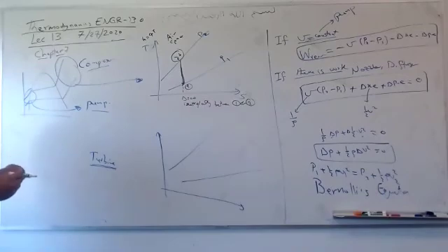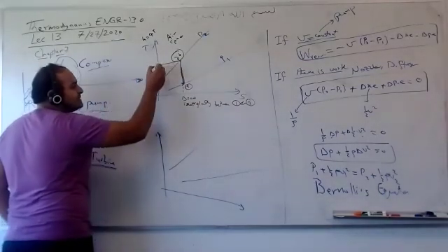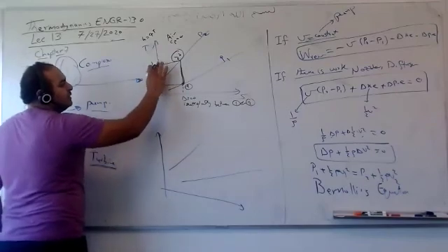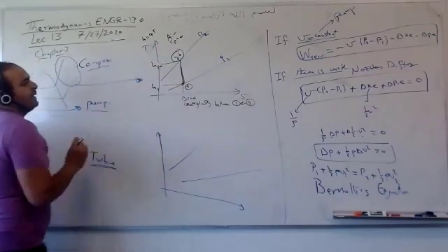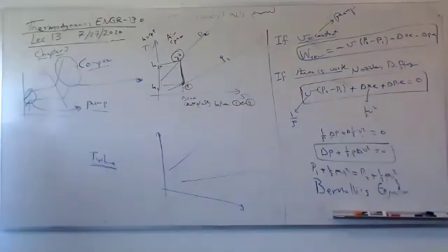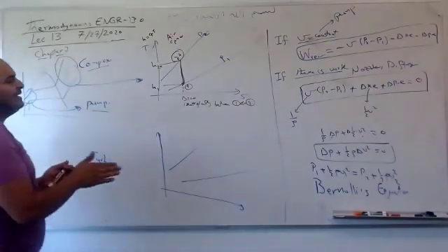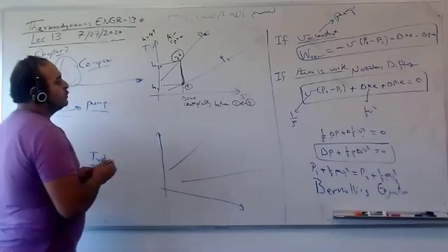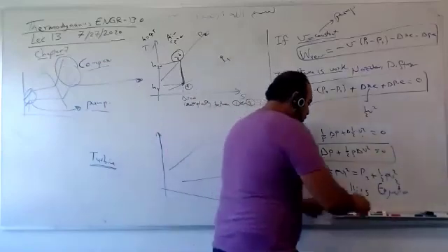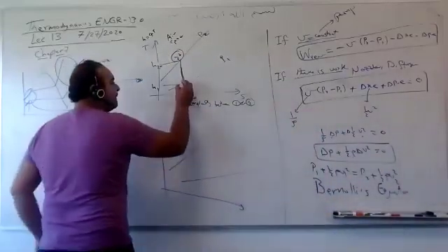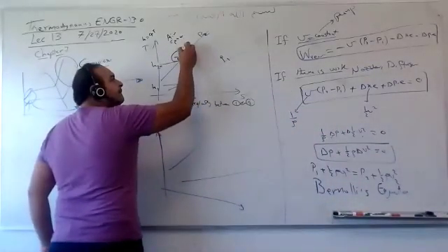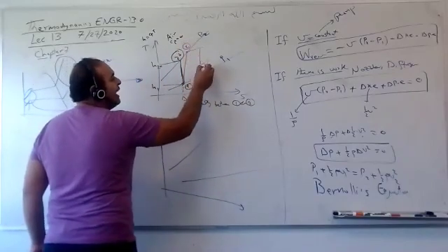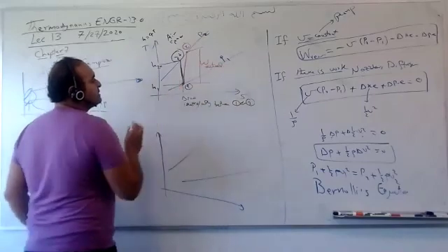So in compressor, I pay work. This work is exactly this distance, h2S minus h1. This is exactly what I wish to pay. Unfortunately, we have some friction, we have some heat, we have irreversibility. So entropy is generated. So we move in reality along the blue or red line, like this. This is actual. So we pay more. That's W actual.